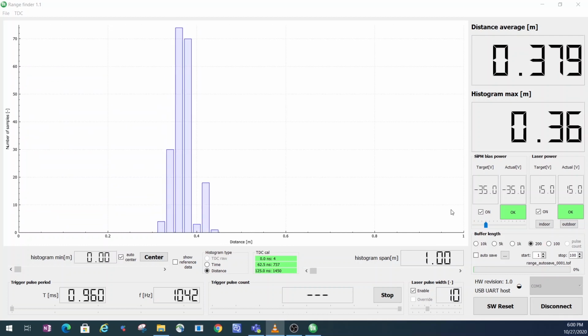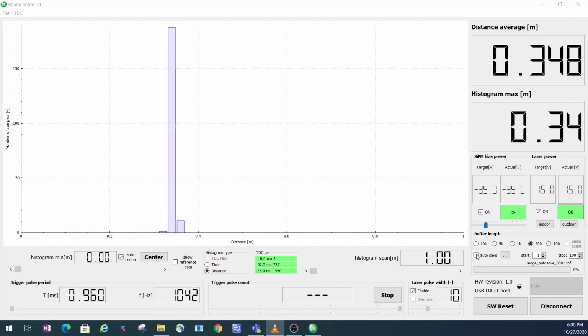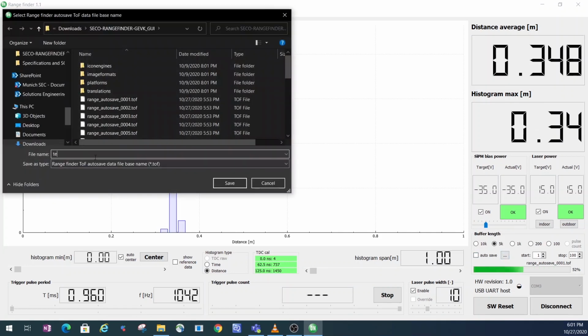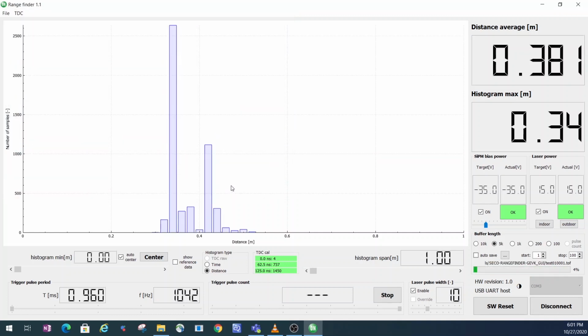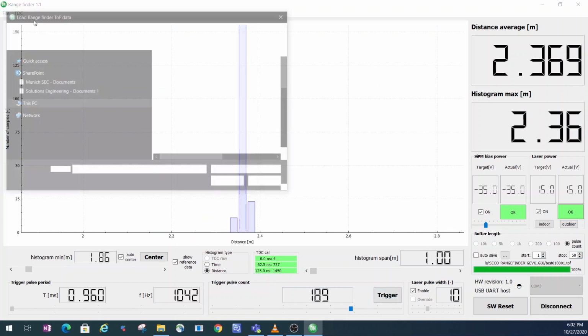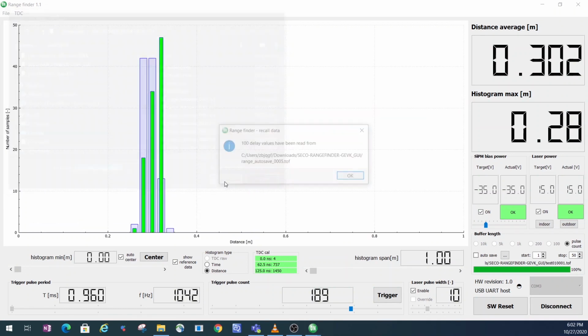The tool allows to save the measured data in dToF files, both in the trigger and continuous modes. For that, the Auto Saves checkbox needs to be selected, and you can set a specific directory for the exported files, as well as a name, for example, test01. In continuous mode, you can limit the number of measurements saved, same as number of dToF files generated, with start and stop input text boxes. All the saved dToF data files can be loaded into the chart for comparison.